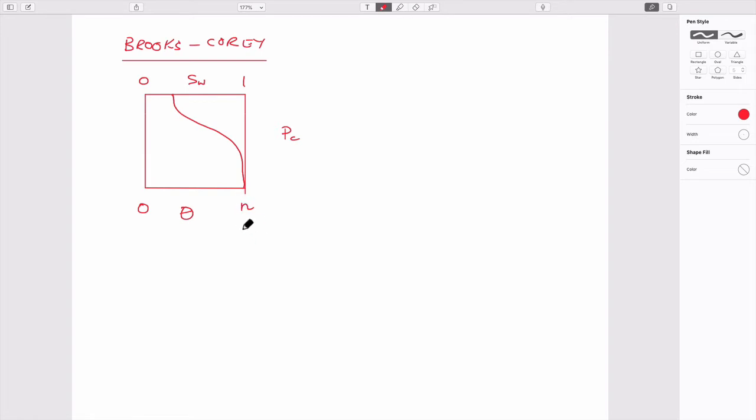We could also think of this as being the volumetric moisture content, which is saturated. And we could think about this bounding value here, which is the irreducible saturation of water, right? This water we can't get out of the system. It's going to be left in it. And I suppose we could define a value of this as the volumetric moisture content that represents the irreducible volumetric moisture content, just as a parallel to this.